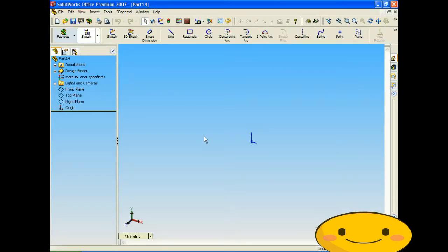So we're going to be covering how to use the Rotate Sketch feature, and what that's really going to do is, if we have a sketch that we've made and it's a unique sketch, it's kind of hard to duplicate, we're able to rotate that sketch using constraints, rather than using a constraint such as smart dimension, dimensioning each component and kind of rotating it around, or if we had to redraw it and try to guess where it would be. Using the Rotate Sketch is a much easier and more precise approach to doing this.